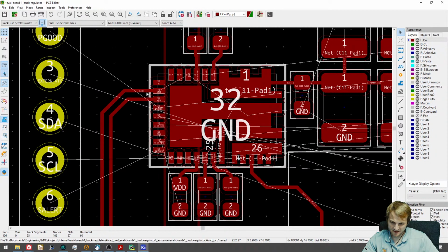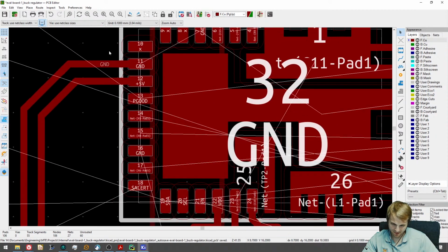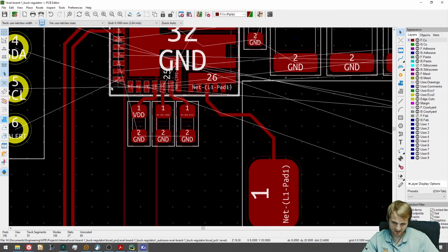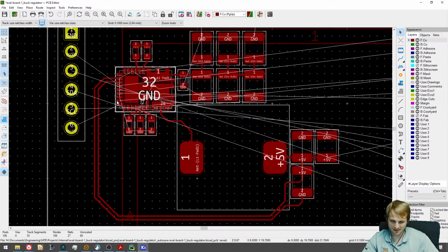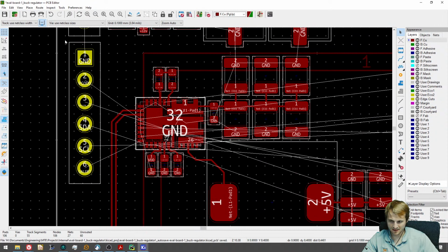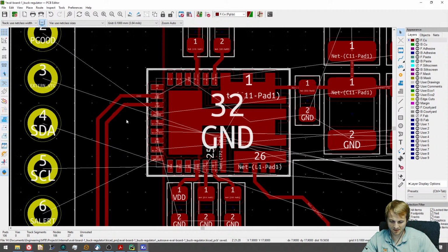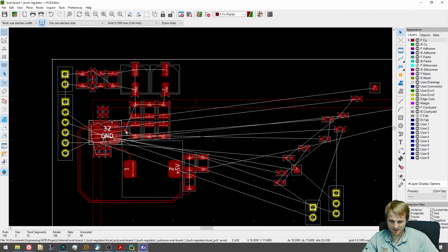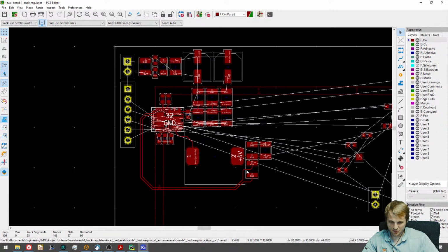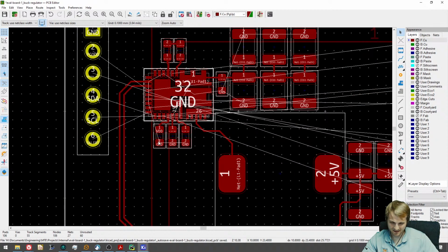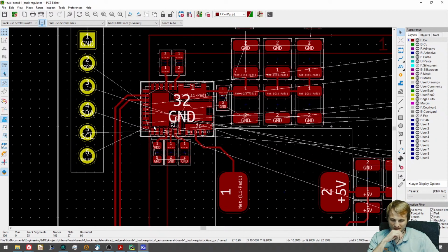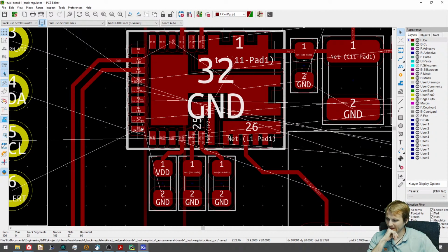Yeah, this is kind of a shame. They should have put these sense lines on the bottom so then it didn't have to cross any of these data lines, because the problem is this goes to the outside world and all of these lines are going to have to cross over our sensitive analog pins, which for obvious reasons isn't ideal. So I still like this IC in the configuration, but that's a bit of a miss.